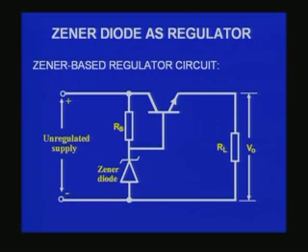That means even though I use a normal Zener diode with about 500 milliwatts power rating, I can still have much larger current than what I would normally calculate as my IZ max, because now I use a transistor. Basically you can understand for the present the transistor as a simple current amplifying device. So if I have a base current IB here, I will get a collector or emitter current which will be several times larger than the base current.